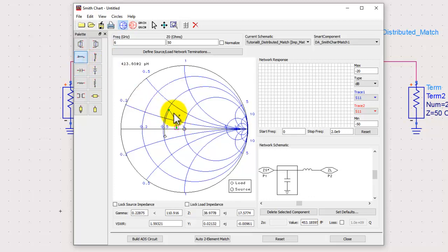Here our objective is not to design matching networks using those LC approaches. We already discussed plenty of things about it, but we will explore how we can implement a distributed equivalent of this kind of network. But remember, no matter what you do, all the distributed transmission lines eventually represent some form of inductor and capacitor. These are the primitive components. It's just that we are going to realize them using distributed transmission line theory. All right, so let's delete some of these components.